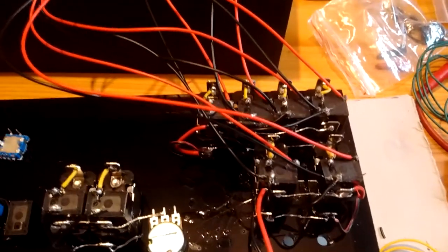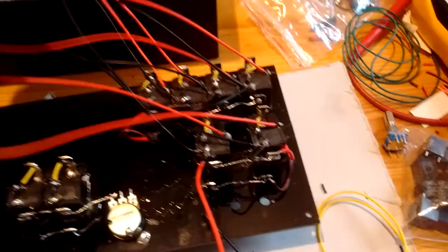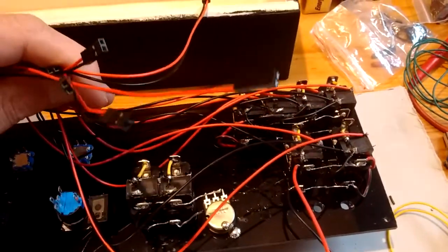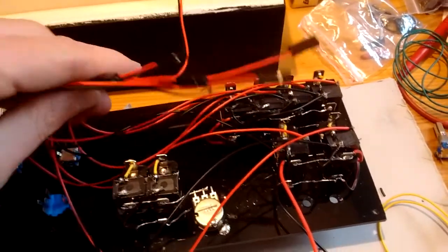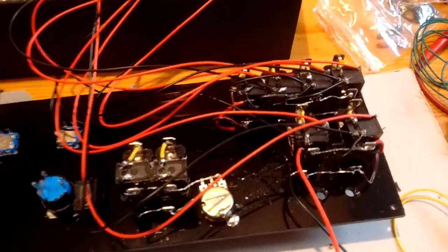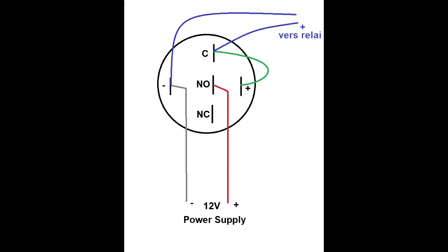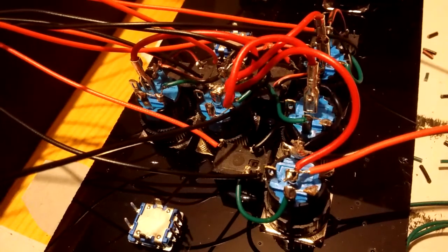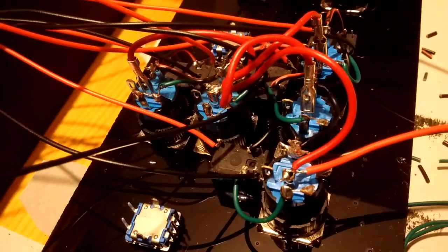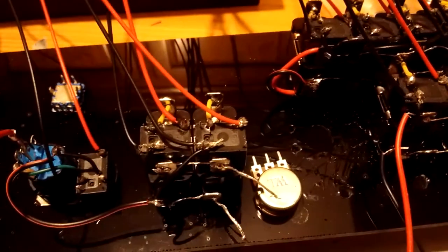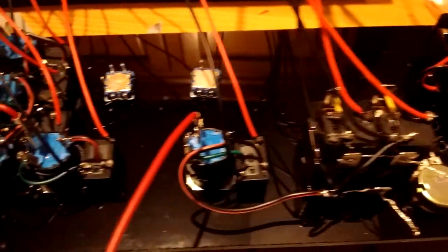I've soldered the DuPont cable, like in the diagram. This cable will be plugged into the LeoBodnar board. Concerning the push button with integrated LEDs, this is the diagram. I don't show the wiring diagram for the relay because it's the same as for the on-off switch. So to see it more clearly, I made some little groups, then I can test them independently, and at the end I will solder all the groups together.